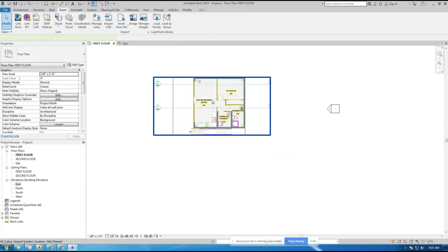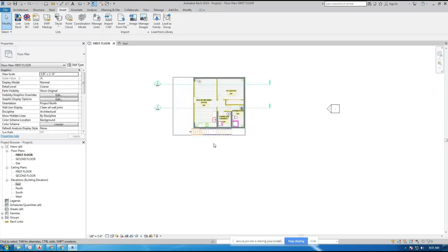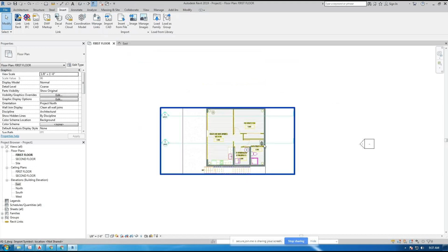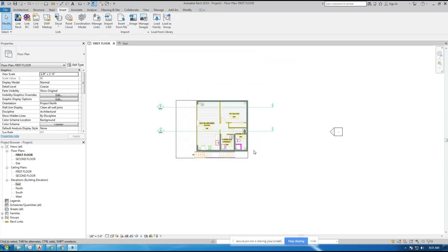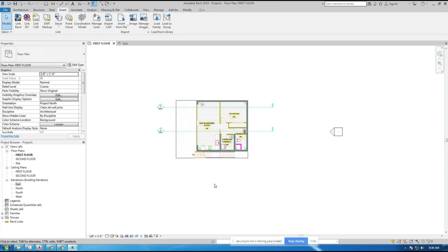That means that currently I cannot move that drawing. It's stuck to the screen, which is good because if I ever had to remove and bring this drawing back into Revit, it puts it exactly in this location, and that's a good thing. So only move this, unpin it, and move this drawing if it's absolutely necessary.